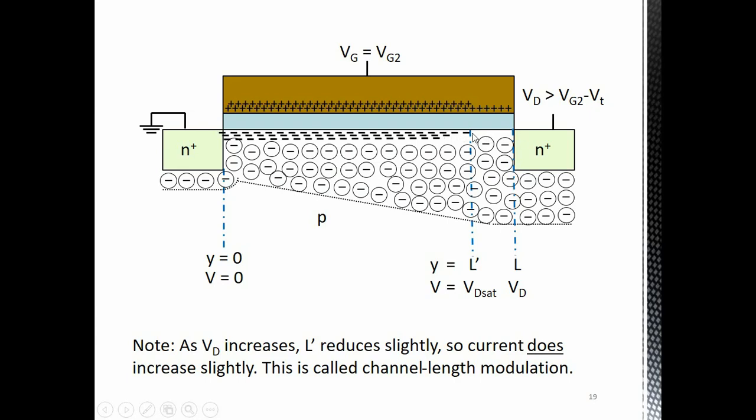Alright, and so therefore there are actually a small number of electrons in this region that sustain the current. The reason one says that they are not inversion layer electrons is because if you actually do a two-dimensional simulation, one finds that when they are swept across, the electrons will be all over the place.